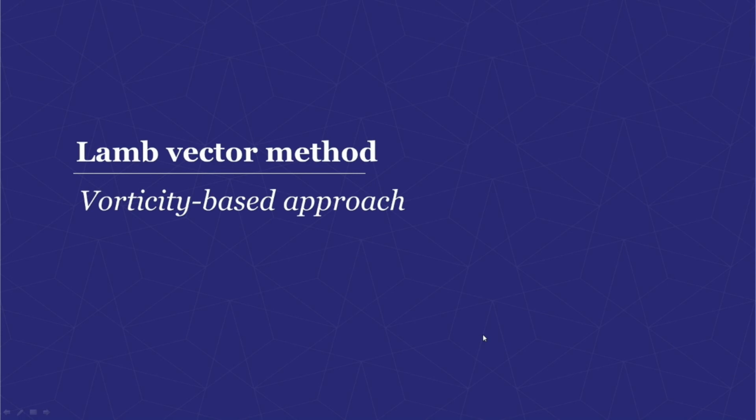But there is another, completely different method called lamb vector, that allows you to also perform an aerodynamic analysis, but this time fully based on vorticity. This is a completely different approach. Let's go for it.